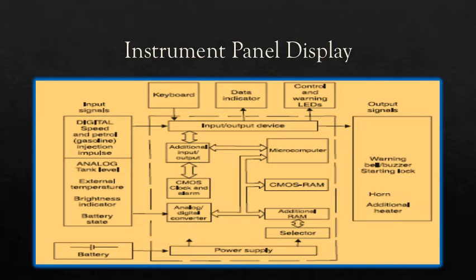Most of the processor based designs use an application specific standard processor, ASSP, or a system on chip, SoC. In this application specific standard processor, all peripherals like digital and analog inputs and outputs, LCD and stepper motor drivers, lamp drivers, etc. are integrated with the CPU core as a single IC. This not only reduces the cost but also enhances the reliability.